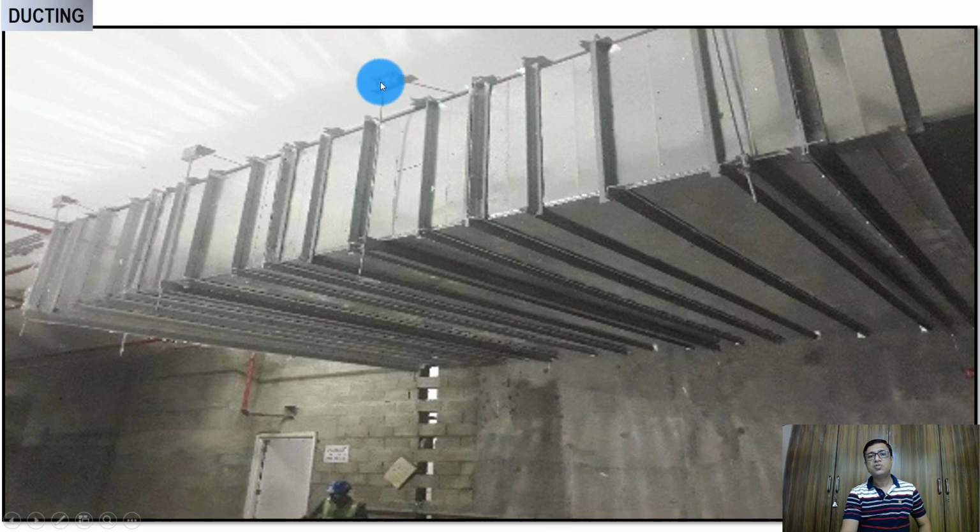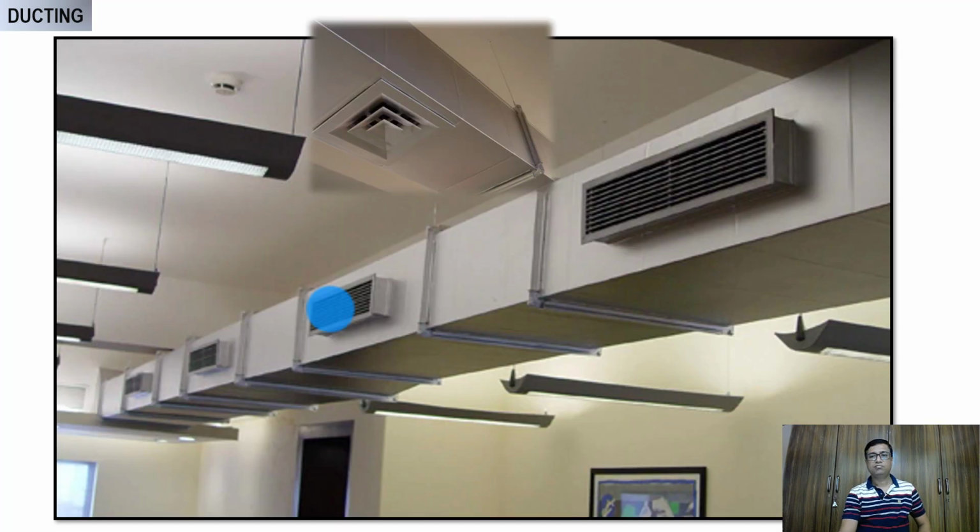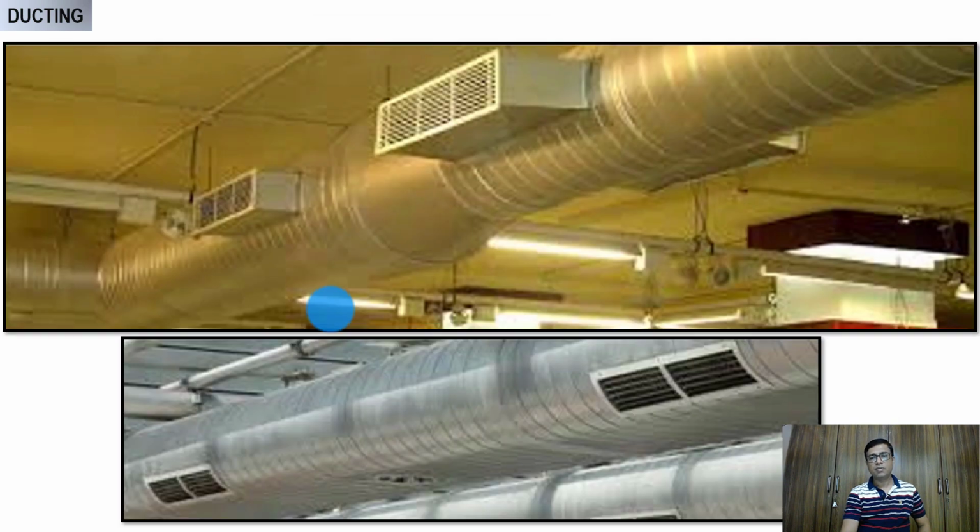There are two fasteners which are used over here, and from there a C channel is pushed inside with two fasteners, and from the C channel we are taking support here. So this is how the ducts can be constructed and installed, which is a good way of doing the ducts. This is another picture which shows how beautifully the ducts are installed. Another good looking duct. There are circular types of ducts also, or elliptical ducts. These are some of the examples.